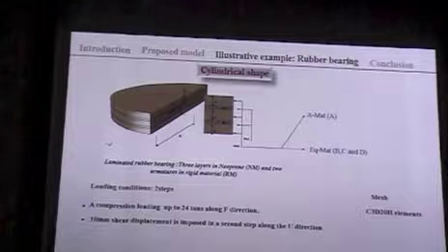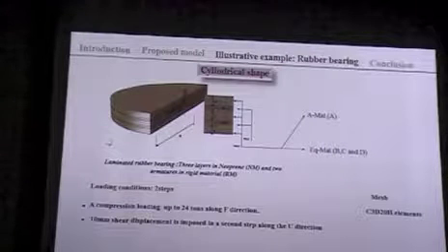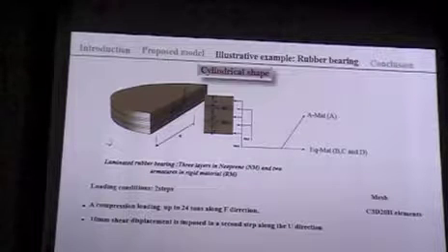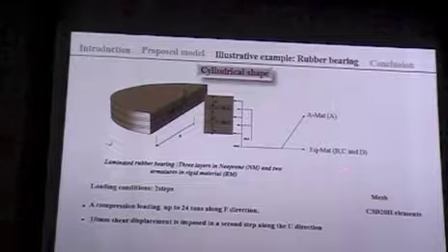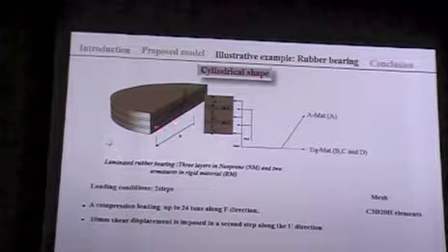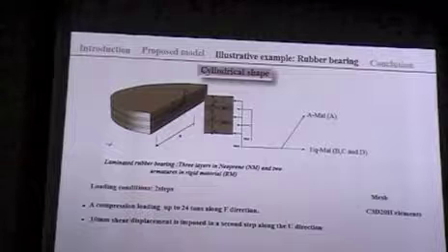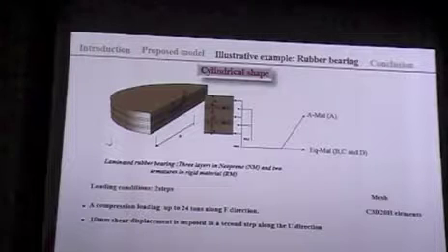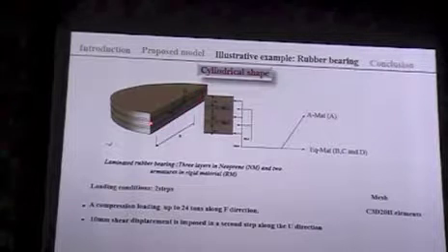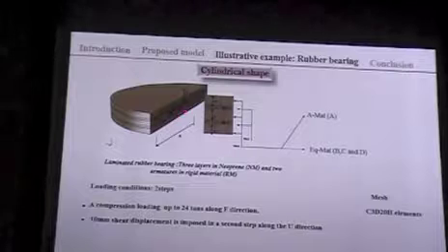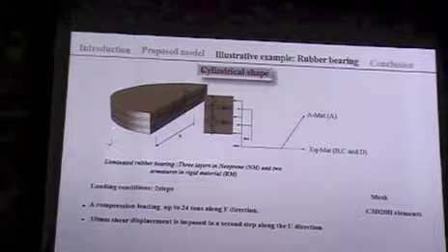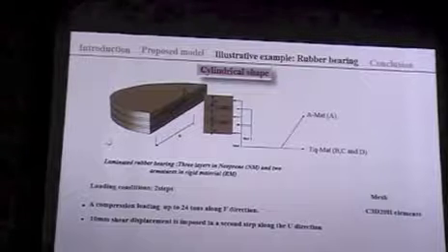This configuration is for two types of material, material A and equivalent materials. Material A means that the three layers of neoprene are the same, with the same compressibility and the same coefficients of the Mooney law. For the equivalent materials B, C, and D, the material is neoprene, but the compressibility modulus is different, and the material parameters are different.